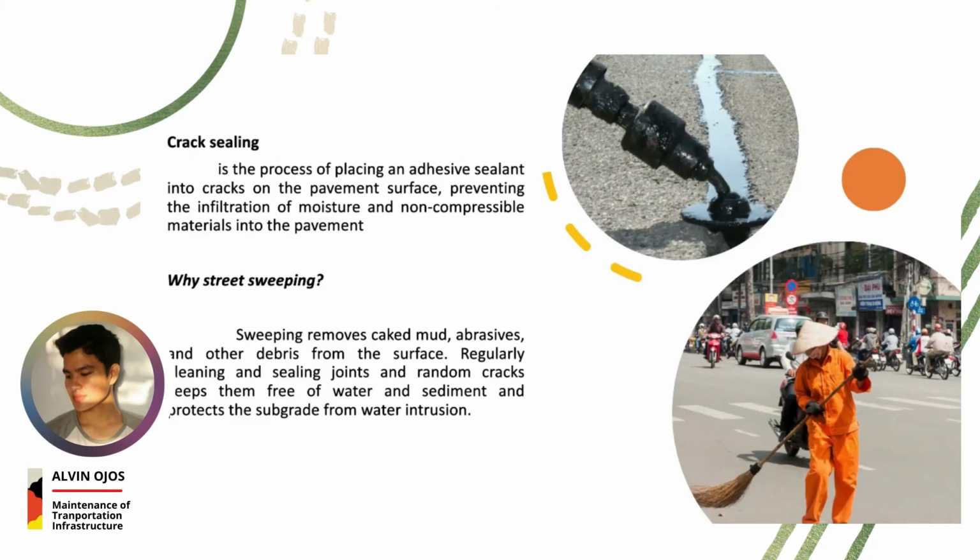So first we have crack sealing. It is a process of placing an adhesive sealant into cracks on the pavement surface, preventing the infiltration of moisture and non-compressible materials into the pavement.